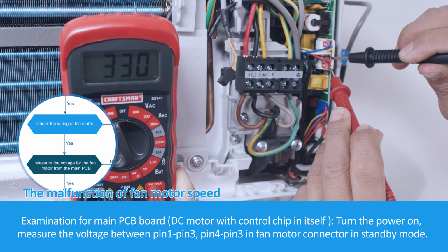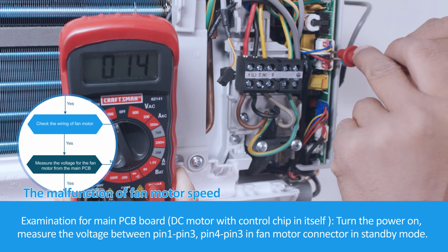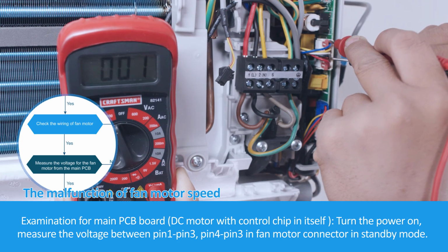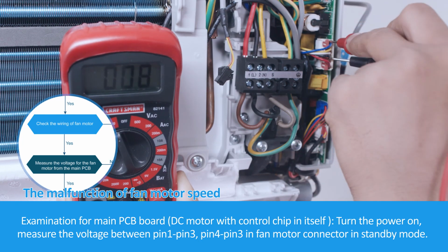Examination for main PCB board. DC motor with control chip in itself. Turn the power on. Measure the voltage between pin 1, pin 3, pin 4, pin 3 in the fan motor connector in standby mode.